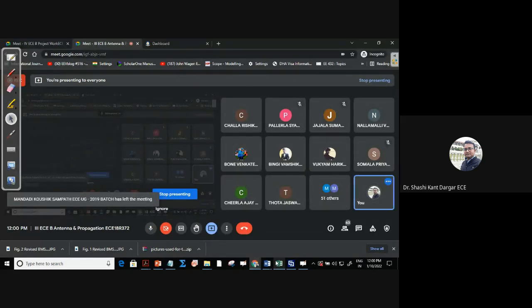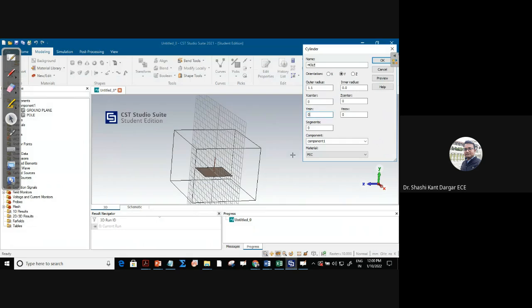Sorry for the interruption again. So here we want to create the hole. What should the y minimum direction be? It is the thickness of this, so I am taking minus 0.02. Are you getting this point? Up to 0, so that the portion we created in the cylinder up to 0 will be removed. Are you getting me? So y minimum is 0 and y maximum goes up to 0.2. 0.2 is the thickness of the ground plane also. So that's what we removed now.